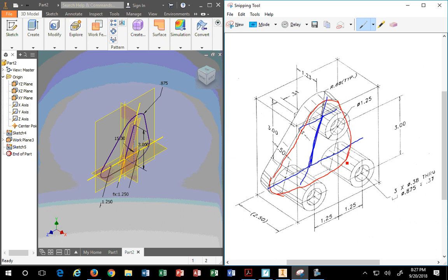We have this shape in the back. See that? We have that shape. When we extrude it, we have to think which way we want to extrude it. You cannot extrude forward because your 3-inch parameter is based on the front face. So you have to extrude backwards.